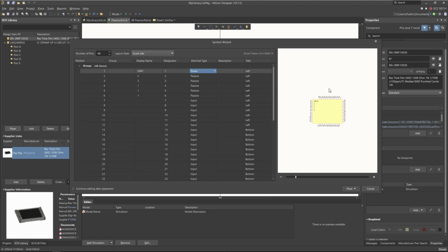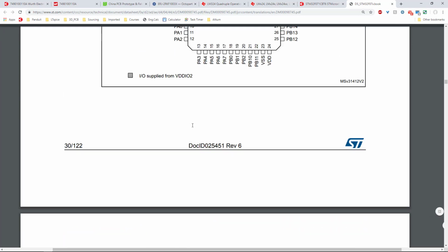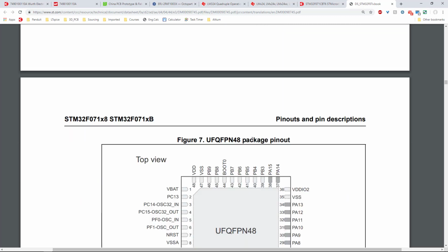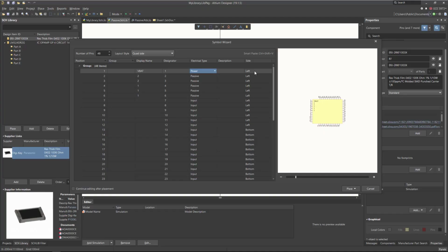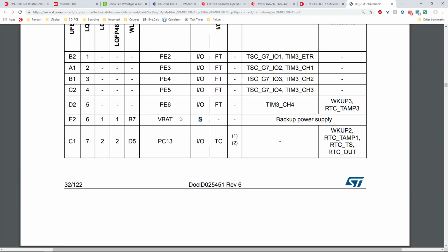It doesn't matter. But if you want to have it similar to this shape on the schematic and footprint, the same thing. So pin number 1 always starts from the top left. So you can have it in here as well on the left side. Okay, it will start in here. So let's go back to the table and we need to create the rest similarly.